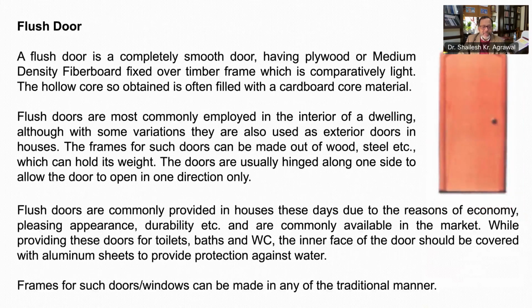Now let's see the flush door. Flush door is completely smooth, consisting of plywood or medium density fiber board fixed over timber frame. The hollow core so obtained is filled with cardboard core material. They can be used for exterior as well as interior applications.